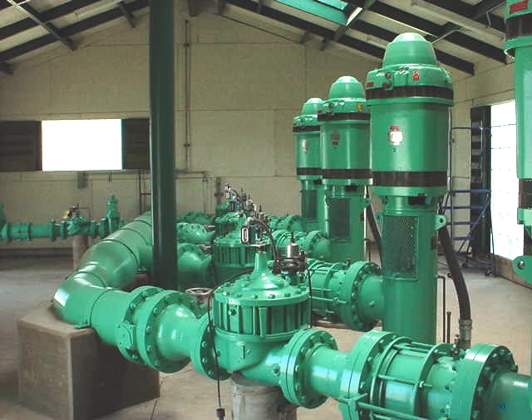And then here's that auxiliary valve. So these valves right here are going to be closed, and as the pump is started against this closed valve, it'll slowly push this open, and then discharge that water out into the system without causing any kind of water hammer.